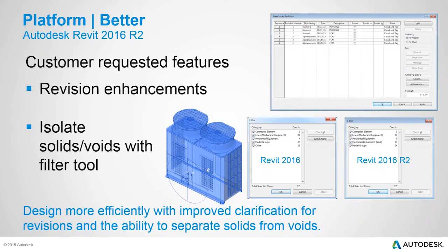Okay, so the way we've done this is the geometries that are not assigned to a specific subcategory show up listed under the families category instead of just displaying other. Okay, the same differentiation is also available in the element properties dialog box. So you can see this information in the properties box as well, so that's quite useful.